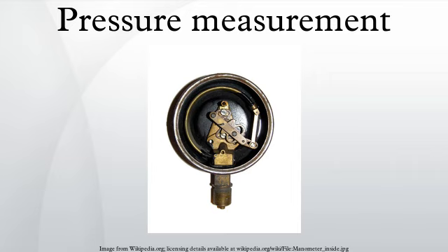Although any fluid can be used, mercury is preferred for its high density and low vapor pressure. For low pressure differences well above the vapor pressure of water, water is commonly used. Liquid column pressure gauges are independent of the type of fluid being measured and have a highly linear calibration. They have poor dynamic response because the fluid in the column may react slowly to a pressure change. When measuring vacuum, the working liquid may evaporate and contaminate the vacuum if its vapor pressure is too high.